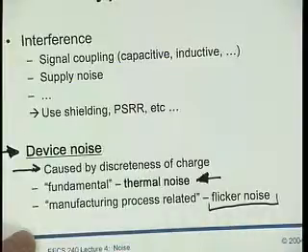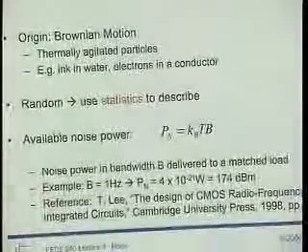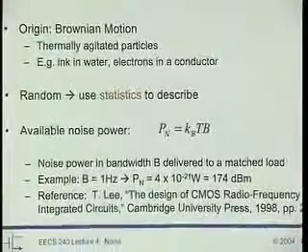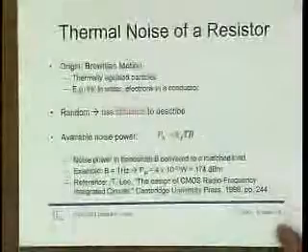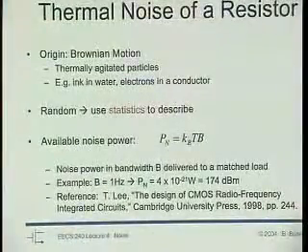In thermal noise, it's more complicated. You can do it sometimes, but if you try to get rid of noise in thermal noise, it usually means more power. Okay, and you don't really get rid of the noise. You just make more signal or so. Okay, so with that, let's start looking at the phenomenon of noise, and we look at noise in the context of a resistor.